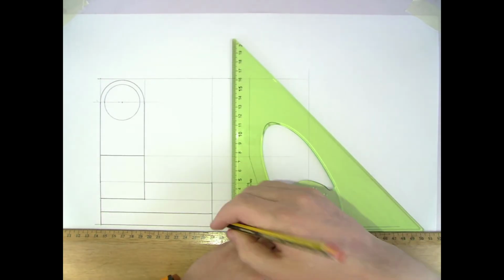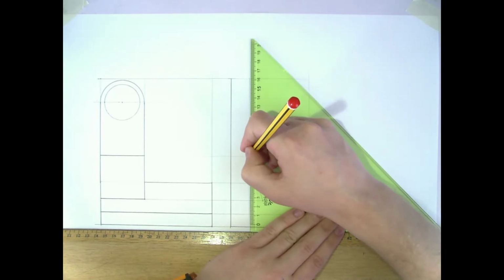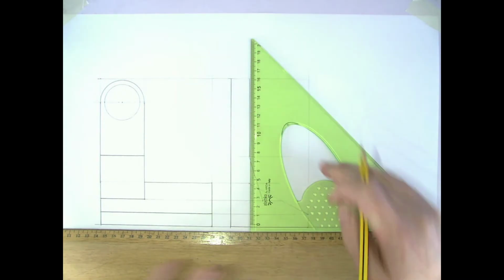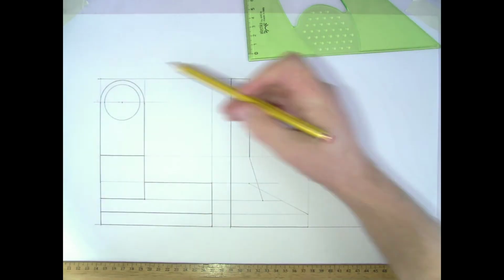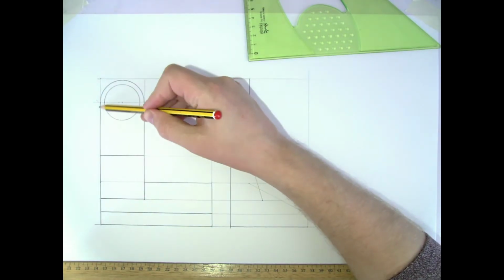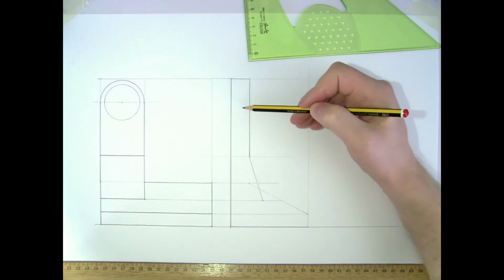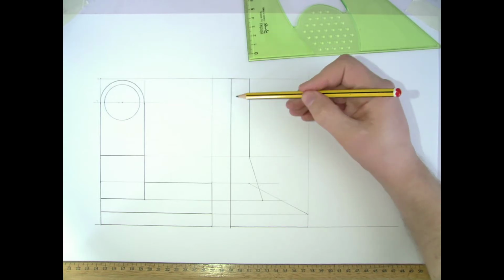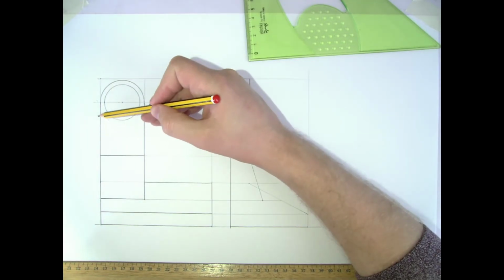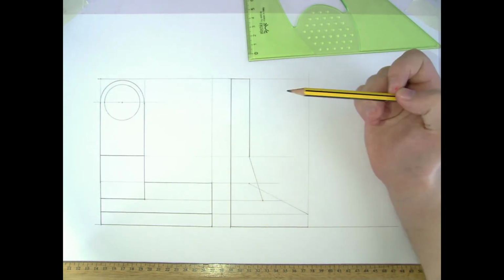This back line goes the whole way up, and it comes down as far as here on this side, and I can just darken in that little bit up on top. Although this changes direction from a straight line into a curve, there's no edge line here because it's a tangent curve. If it wasn't meeting it tangentially, there would be a curve, but as it's from one line going straight into a tangent circle, coming back down, there's no line here to indicate that.